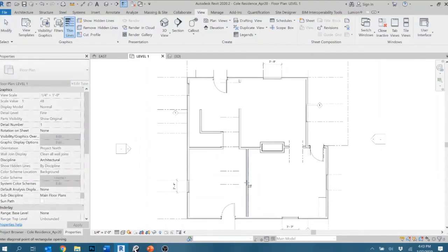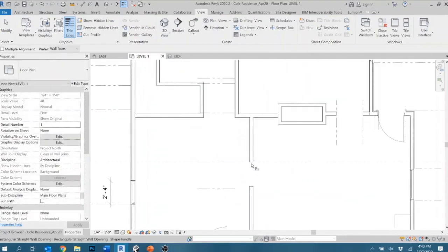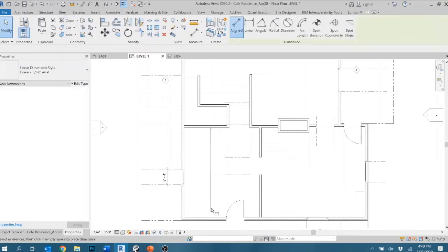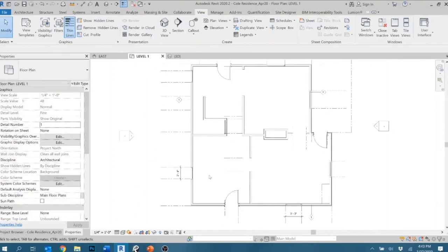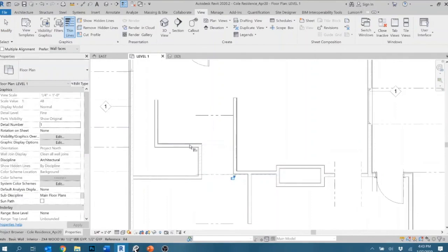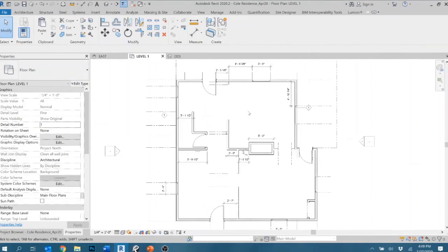I'm going to place another wall opening. I can align the edge of that opening using that. And finally, I knew my last dimension was 13 foot 7. And so I had made the kitchen 13.7 prior to this. So using those offset lines, adjust your walls accordingly. Let's do a stair up to level 2 and down to the basement.